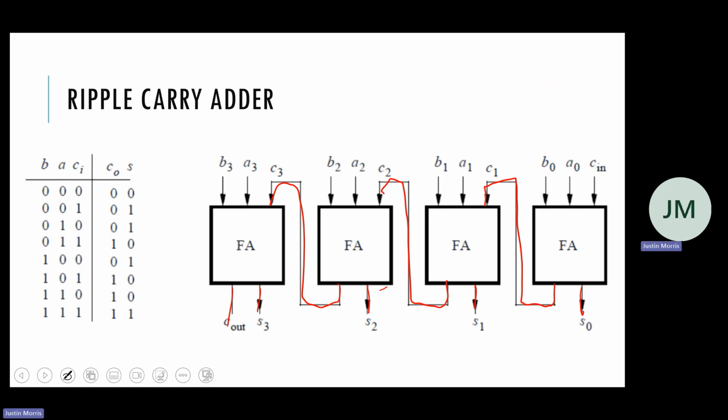And you'll be writing your test bench for this, testing it. So 4 bits, 2 inputs. You have many different combinations. It might not be very practical to test every single combination, right? So in this case, our best practice is, yes, do some normal tests, some edge case tests, right? So edge case tests would be like try making sure that you put in an overflow one. Maybe another edge case is just 0 plus 0, things like that.